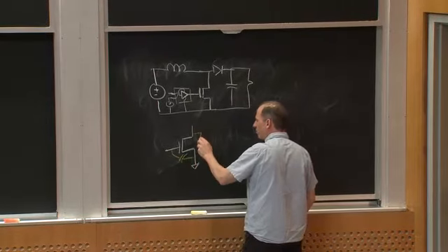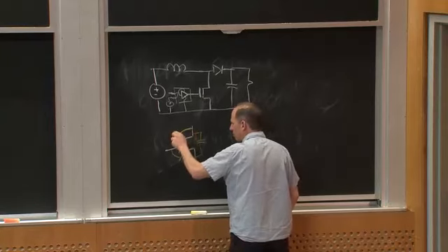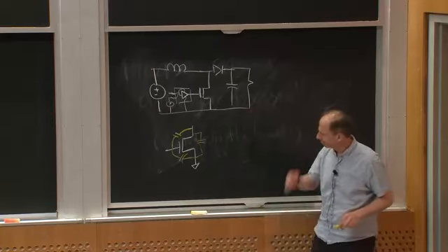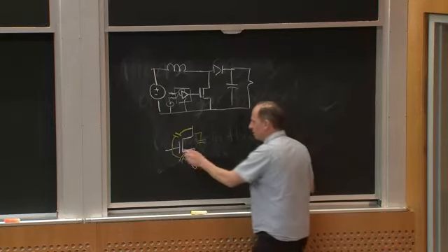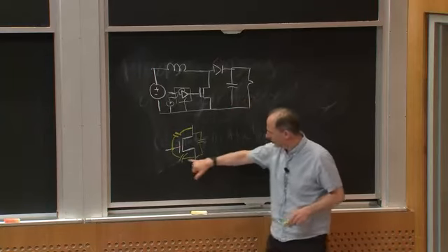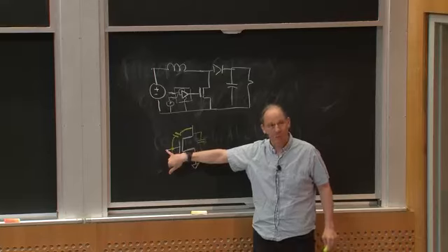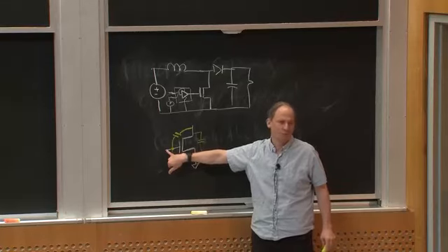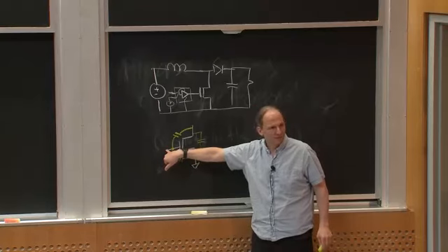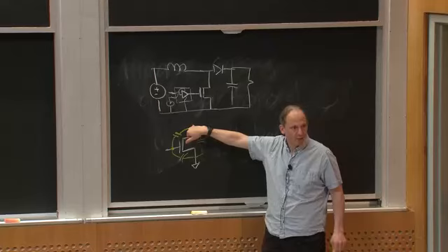He's going to have some drain source capacitance, but he's also importantly going to have some gate to drain capacitance. And this gate to drain capacitance actually has a significant influence, especially when I'm driving this between 0 and 10 volts, or 0 and 5 volts if it's a lower, logic level kind of device, but maybe this drain node is switching by hundreds of volts.